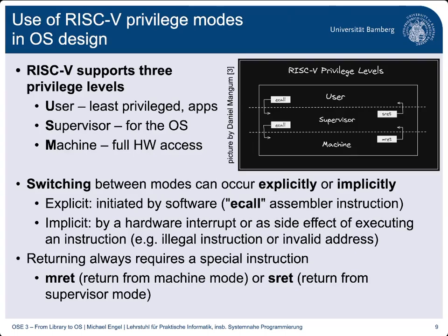So it could also happen that you have something taking you from supervisor mode, from your S mode, to machine mode, and then if you executed an mret in your machine mode code, you would just be back in the supervisor mode, executing with supervisor privileges.